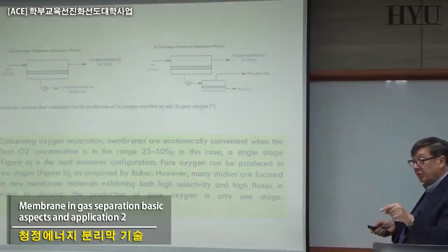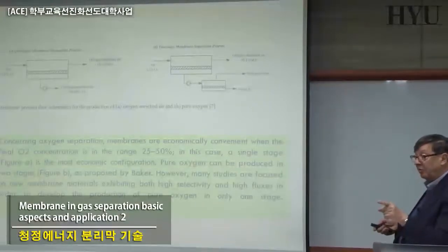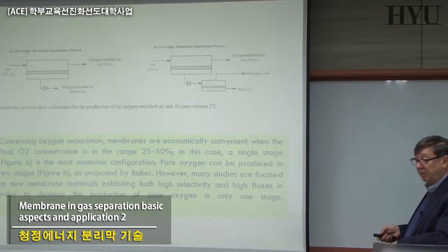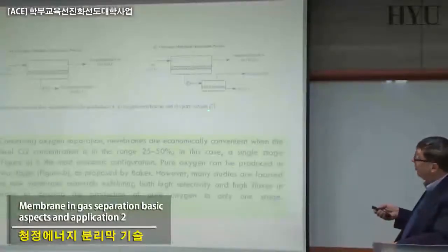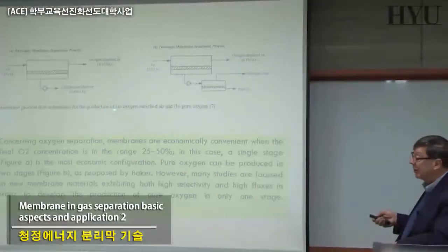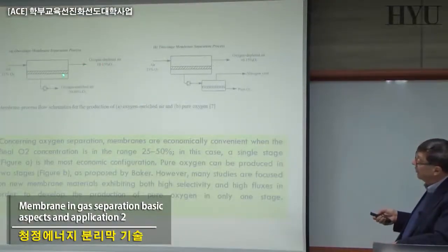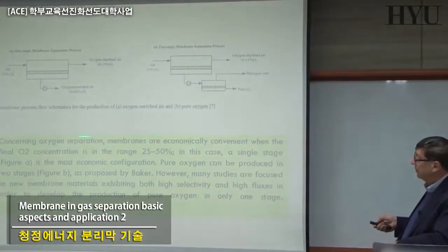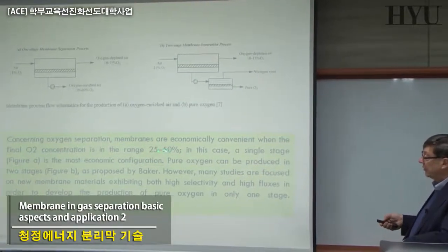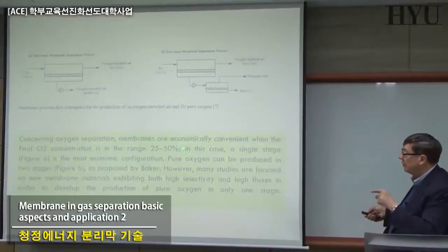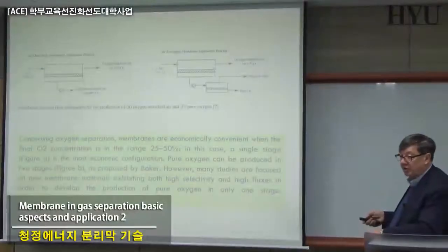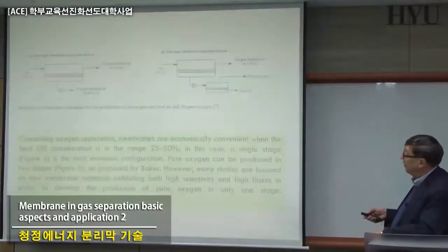As I was mentioning, not all the problems can be solved just by using the existing membranes. So more and more, you will see also in the gas system this kind of solution. This, I think, if I remember, is the case of Richard Baker, that there's the oxygen separation. And in this range of concentration, with 25–50%, this is competing with cryogenic, with the existing membranes. But you can make it better if you want to also increase.